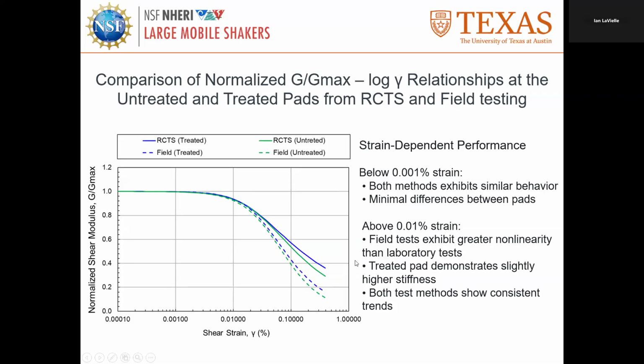And I think we ran another test last week and I tried to find out why. It might be because of pore pressure buildup, but our pore pressure is not reading correctly. But I think what we have found is that when we have a larger strain with a different frequency, our Gmax might be a little different. So we have some additional test data from last week. Once we correct it, I think it's going to be closer to our test result, and there's no pore pressure buildup. It has to be.